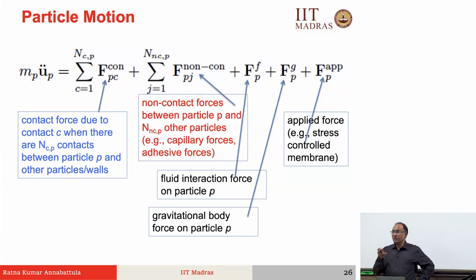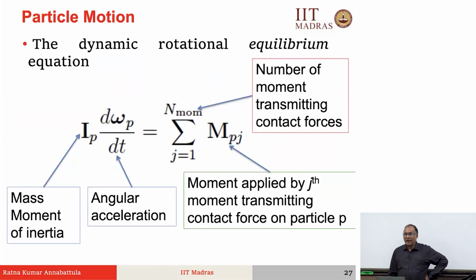So, in principle you have to add it if the material requires. For example, what are we talking about here? We are talking about a particle. The contact force coming from the particle will have all the damping and everything embedded in it. In addition to that, for your simulation to converge, you might have to add some artificial damping, something called numerical damping, for your equations to give a meaningful solution. That means they should stabilize within a reasonable time. Okay.